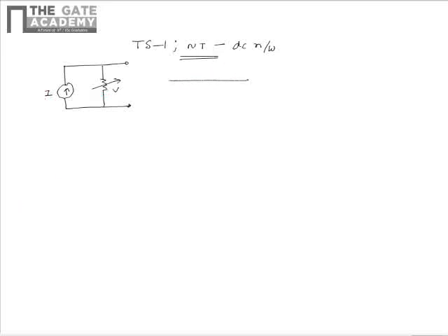and the whole VI characteristic of the variable resistor are as shown. The characteristic intersects with the y-axis at -2 ampere and it intercepts with the v-axis at -30 volts. We need to find the maximum power dissipated in the variable resistor PV. We need to find the maximum power that gets dissipated in the variable resistor V.